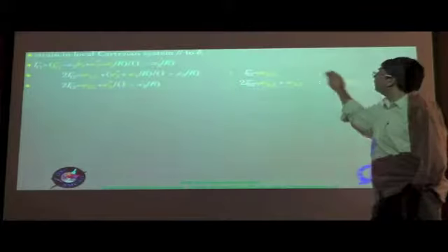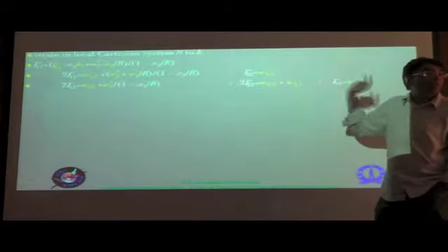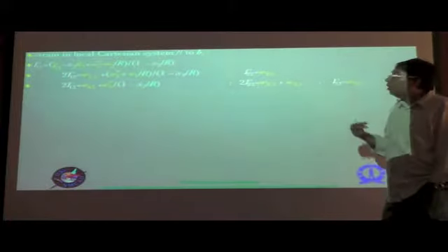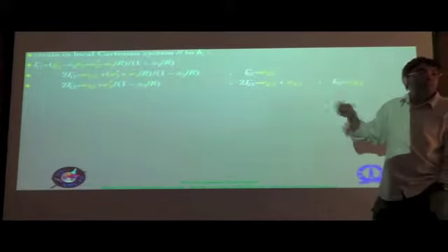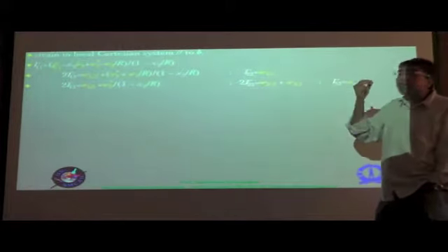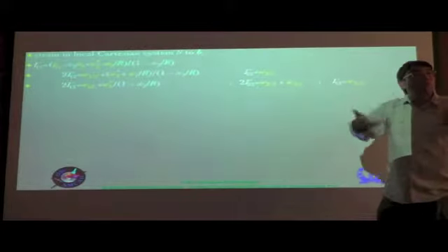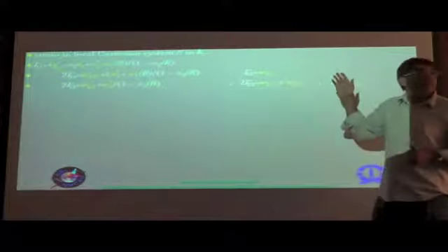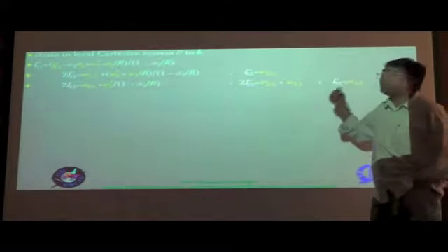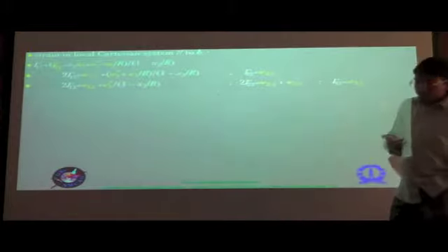The diagonal terms are of course the normal strains, and the off diagonal terms are the shear strains that are involved. Now it's very interesting to see that these 3 strains are dependent only on the W's, they're dependent only on the warping. So if in a particular problem or in a particular model you're completely ignoring warping, for example, it basically means that these are 0. In fact, we considered a very simplified example much earlier, where we said that the cross section is basically rigid, and in other words, there is no in-plane warping, only out-of-plane warping is there, and therefore all of these terms are equal to 0. But this is a little more general case than that, and we are indeed considering these quantities.